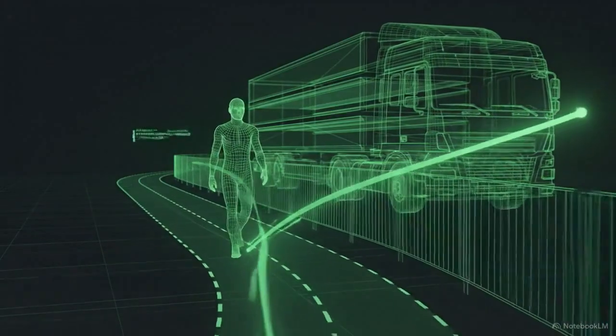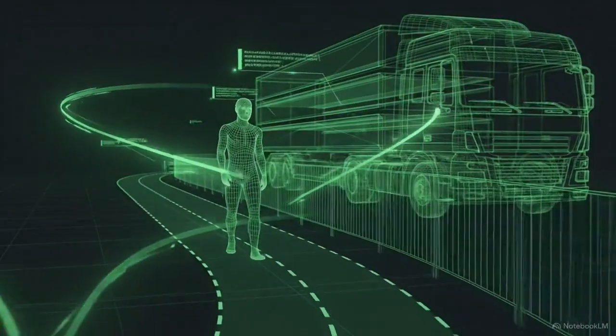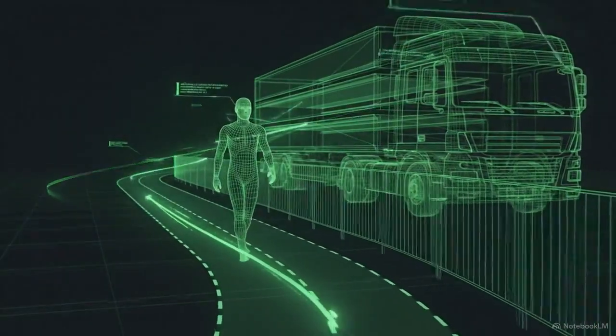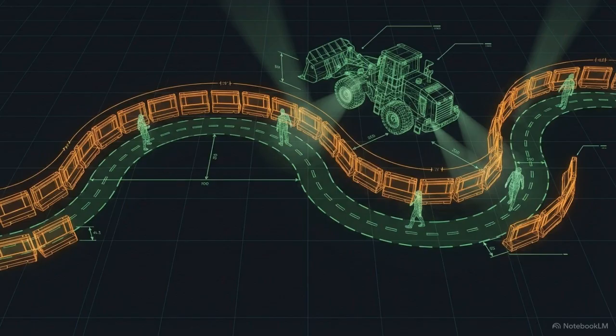Now, perform a quick success check. Can your workers walk from the active work phase to the toilets without crossing a delivery truck route? Centralizing welfare and command facilities in safe, accessible zones prevents massive cumulative losses in labor productivity, keeping unprotected workers out of high-risk traffic areas.